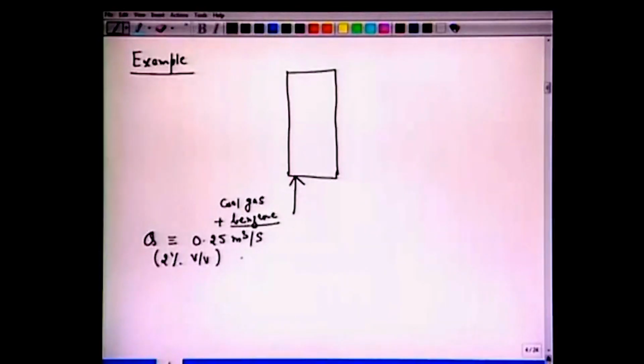Okay, so if you go by the previous nomenclatures which we used, we have here Gs, we have GN, G1. So this would be a solute free basis, or we can call it dry gas. Of course there is no moisture, dry means there is no benzene, based on benzene free solute free basis. So we have Gs, we have G1, we have a small fraction y1, and we have capital Y1, the solute free gas. So these are the four quantities here. Typically we have kilomole per second, or we can also have kg per second just by multiplying by the molecular weight.